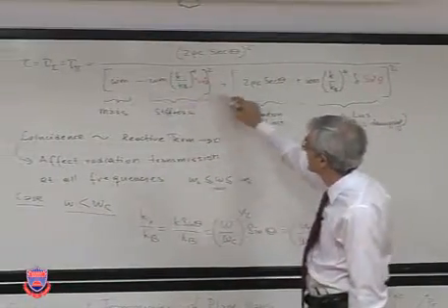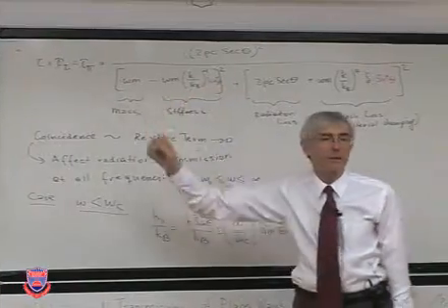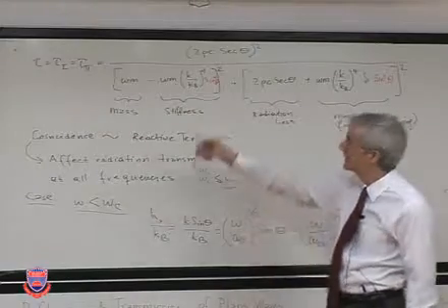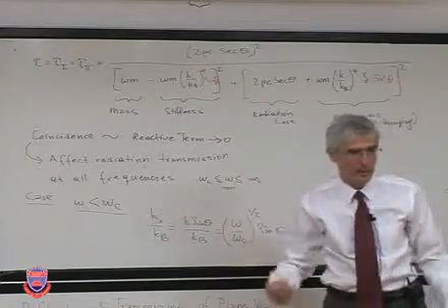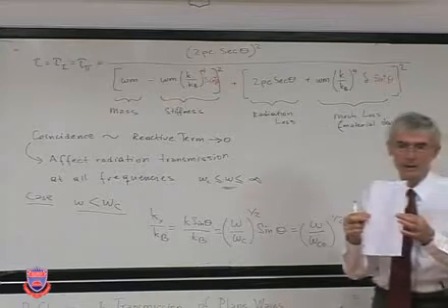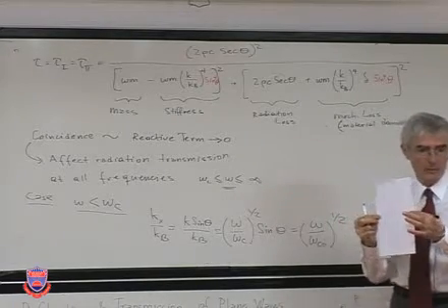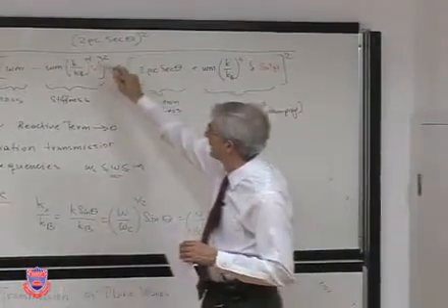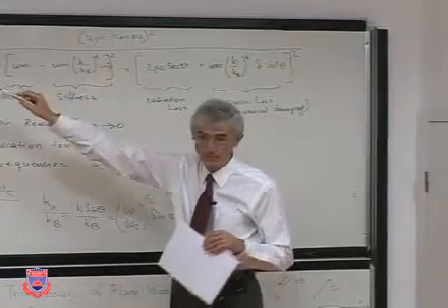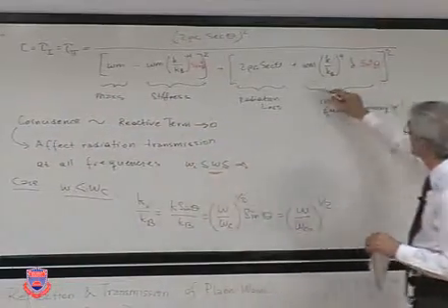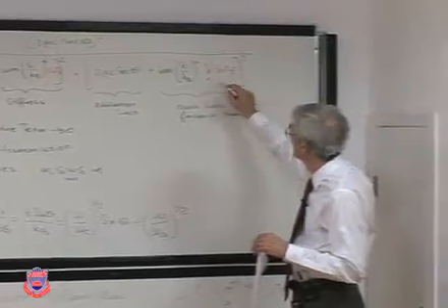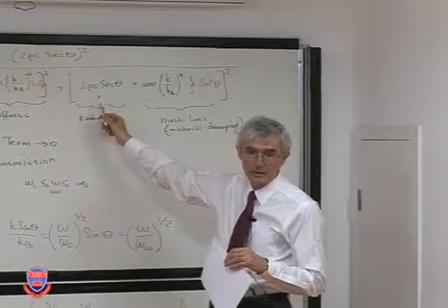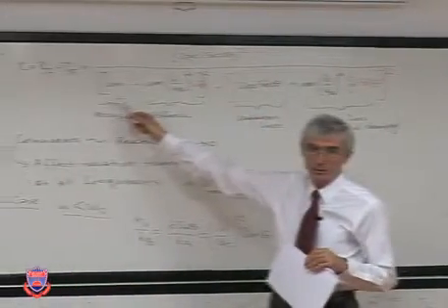First of all, everything is relative. When you say low, we don't give numbers, but with respect to, in this case, the coincidence frequency. And coincidence frequency is determined by the thickness and properties of the plate with respect to the fluid medium. So if this is a negligible term, and also plate damping is negligible, we are left with this term, the radiation term, and the inertia term.